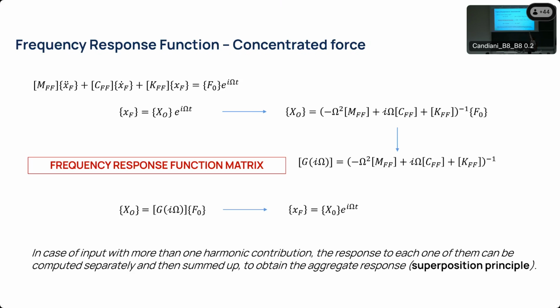So basically, same expression, but in this case, we arrived at it using FEM. During other courses, we arrived there by making different computations, by creating the matrices by hand. So we can obtain what we call the frequency response function matrix. So a matrix of terms which depends both on the position in the matrix as well as the frequency at which we are making that computation.